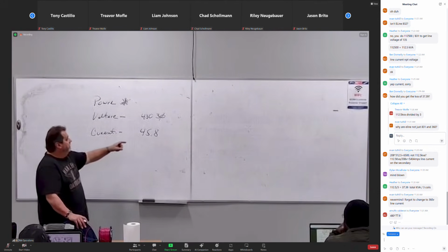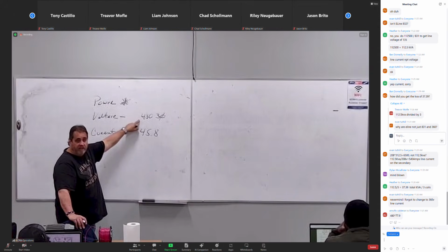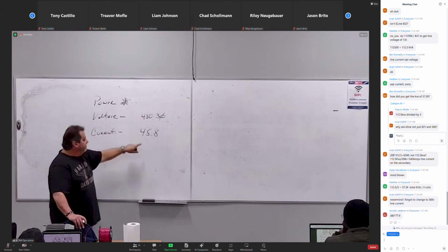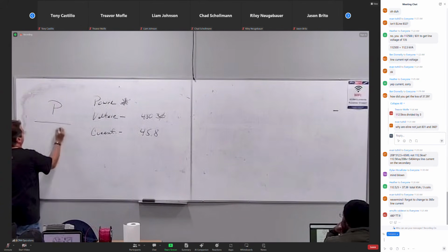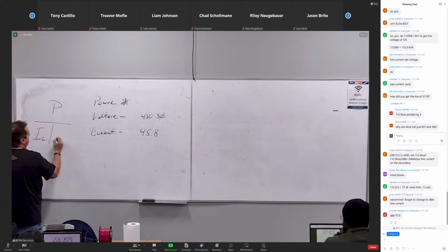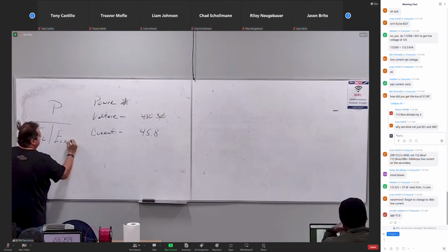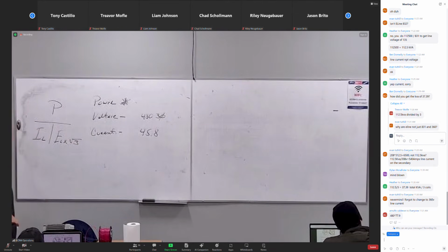Hey guys, you have line voltage, which is what? It's a 3-phase circuit. It's 480 times what? 1.732. I have line current. Solve for line power. It's this formula right here: P equals E line times I line times 1.732. So I'm going to take 480 volts multiplied by 1.732, which is 831, times what? 45.8.